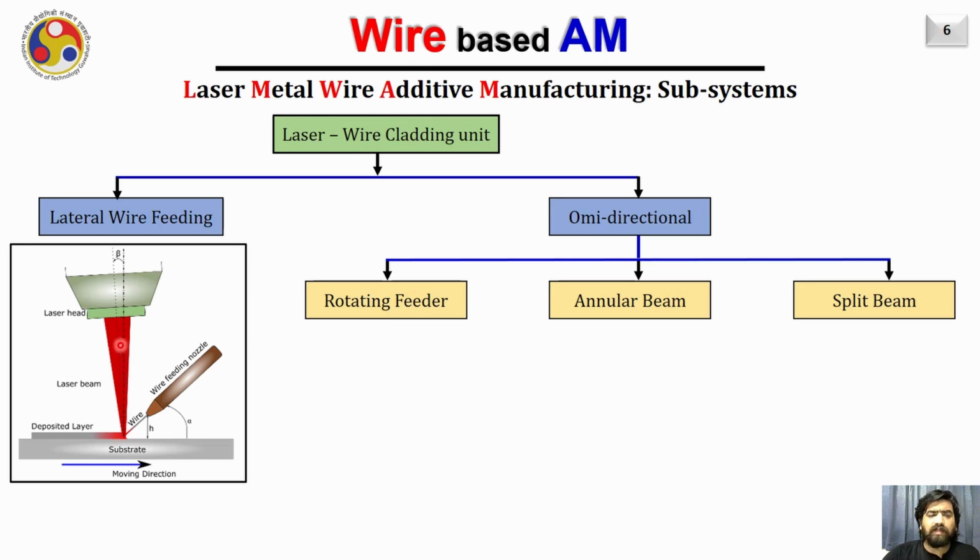One can notice that the laser head is not typically exactly vertical. It is because if there is any back reflection, the laser beam may travel inside the optics and damage it. Therefore, to avoid damage to the optical head, it is slightly tilted to one side in such a way that the laser beam reflected from the surface of the substrate will go somewhere like this, but will not travel into the optical head.